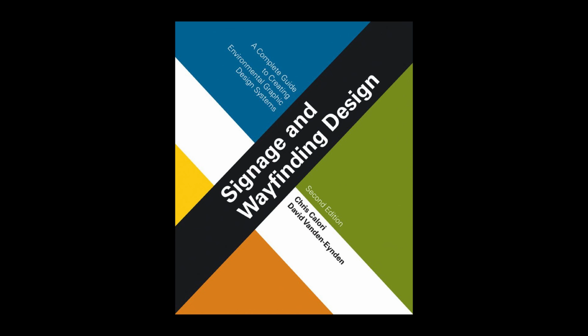Plastic finishes. Plastic finishes are typically imparted in the manufacturing process and are rarely altered in the sign fabricator's shop. The most common factory imparted finish for acrylic and polycarbonate sheet is a completely smooth, mirror-like polish. Although some frosted and other textured finishes are available for these commonly used sign plastics, other plastics used in the sign industry have factory-imparted finishes that range from completely mirror-like smooth to pebbled to directionally grained.